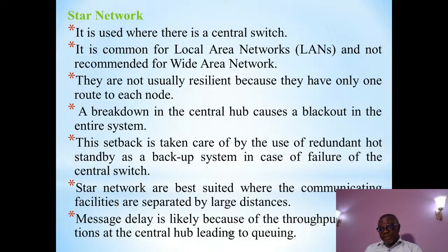You say it has a central node or central switch which connects to all the nodes separately. So if peradventure there is a breakdown in that central switch or central hub, then all the systems experience blackout. This setback is taken care of by the use of redundant hot standby as a backup system in case of failure of the central switch.